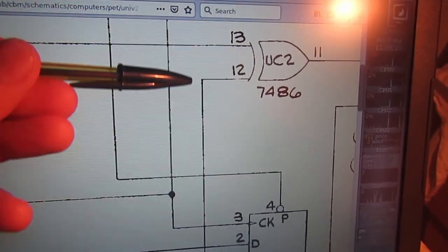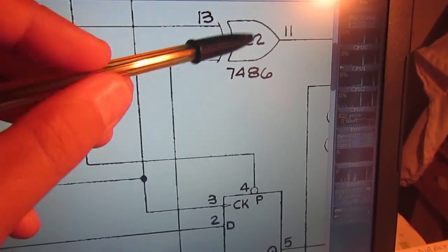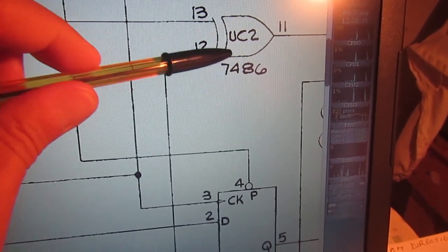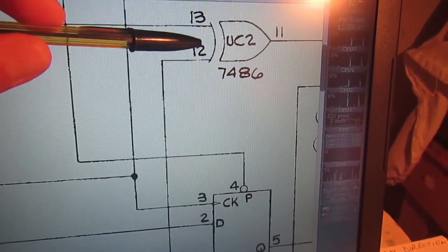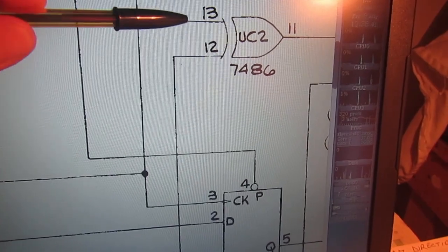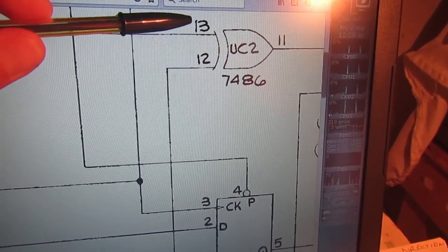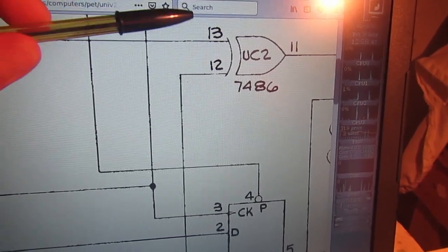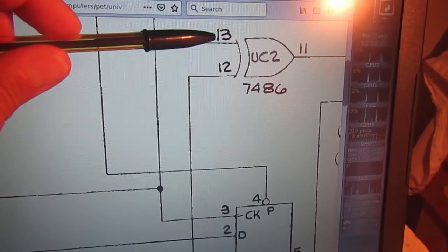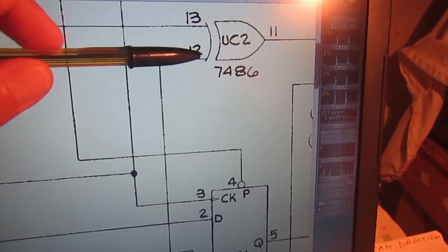and goes where we found the 7th bit from the video RAM goes also. And this is an exclusive OR gate that inverts the video signal if this other input is 1. If this input is 0, so if the 7th bit of the video RAM location is 0, the video signal goes unchanged.